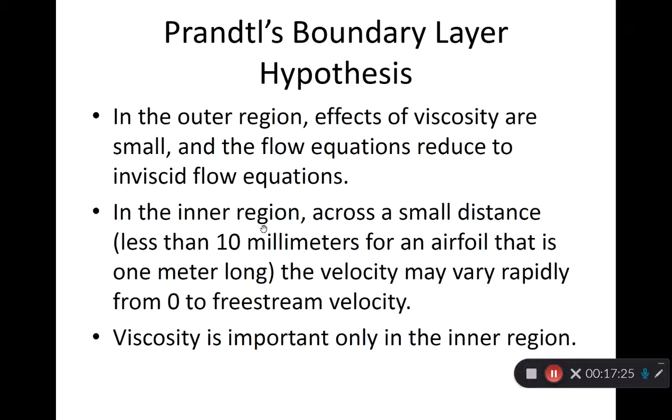On the other hand, in the inner region near the surface, less than a millimeter, sometimes 10 millimeters for an aerofoil that has a 1 meter long chord, the velocity changes very, very rapidly. So in this inner region, viscosity is very, very important.